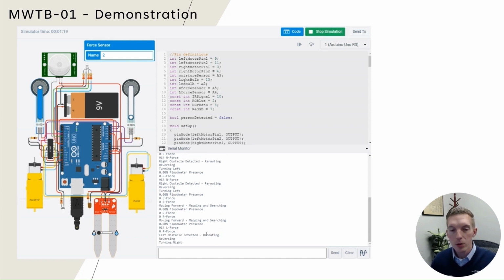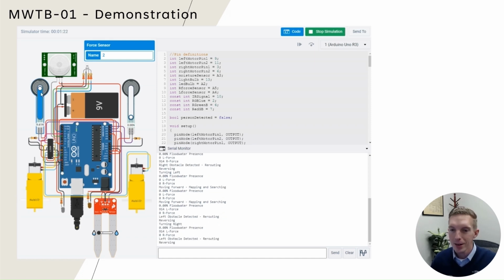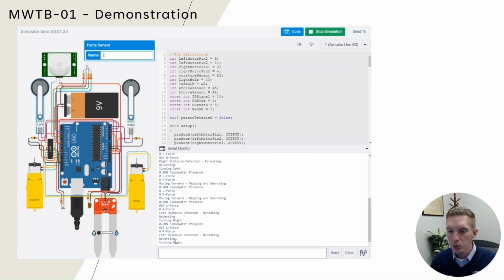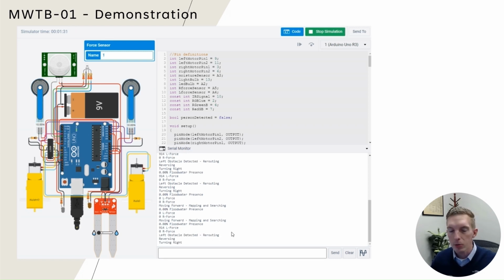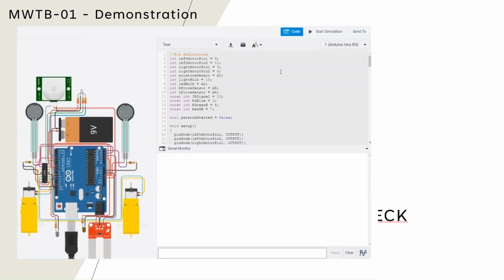Now the other option is, we hit something and it affects both sensors. Well, I couldn't move both sensors at once, so you're going to have to bear with me. It's going to indicate a left strike first, but it will indicate a right strike as the if-then conditions make presence known for both sensors. We're just going to reverse a little bit longer to fix that. All right, and there's the code.